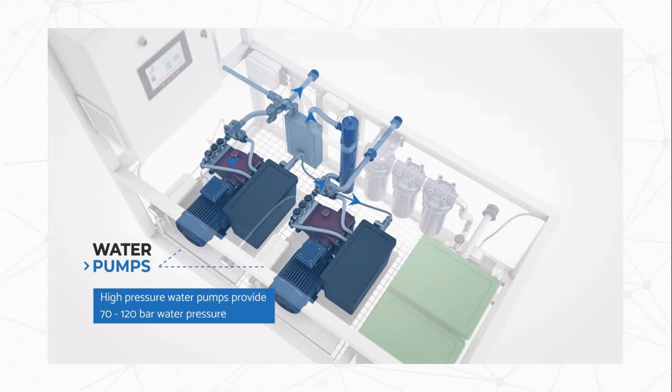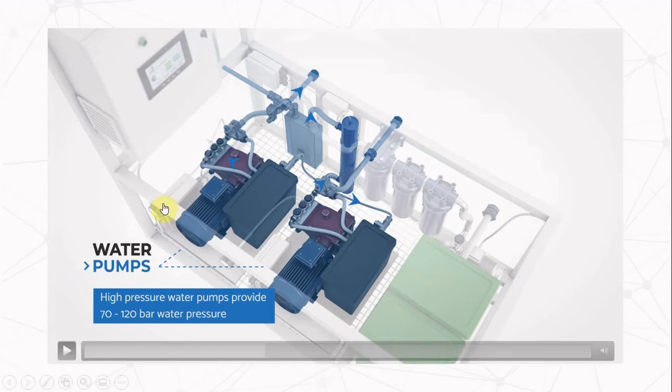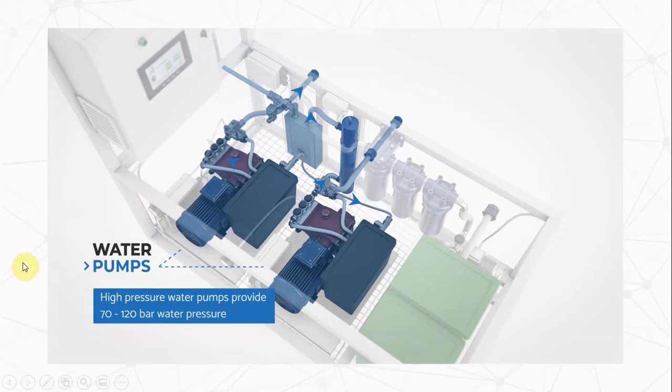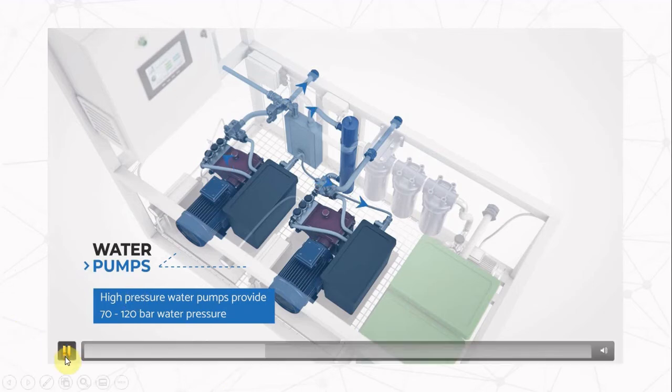On the other hand, if you spray the same amount of water whose droplets are 5 to 30 microns, the water will evaporate immediately and the air temperature will be reduced by 5 to 7 degrees Celsius. This is why we need such high pressure water pumps. It is essential for the process to humidify the air in levels of up to 95%.